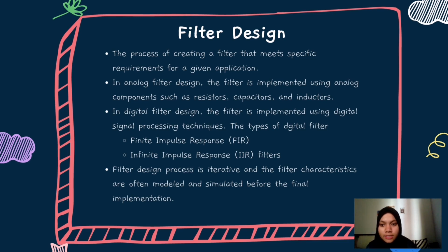In digital filter design, the filter is implemented using digital signal processing techniques. The most common types of digital filter are finite impulse response and infinite impulse response filters. The design process typically involves selecting the appropriate filter type, determining the cut-off frequency, and then calculating the filter coefficients using techniques such as the bilinear transform or impulse invariance method. In either case, the filter design process is iterative and the filter characteristics are often modeled and simulated before the final implementation.